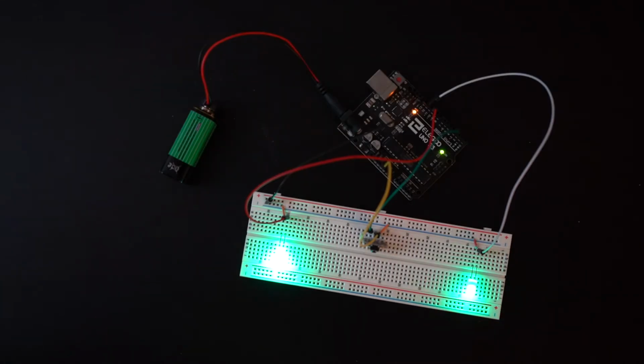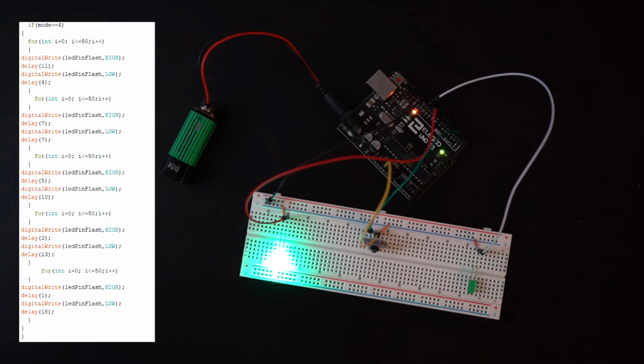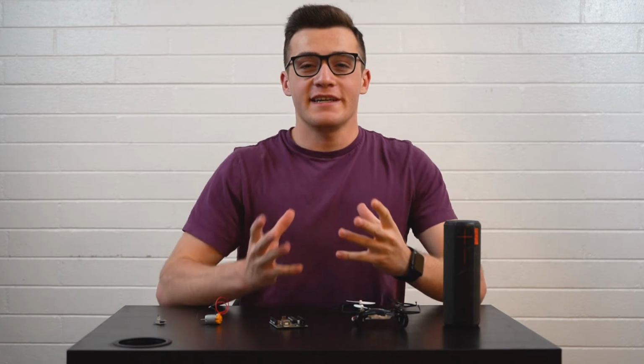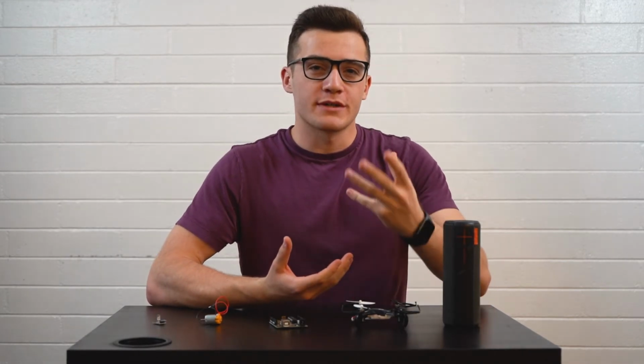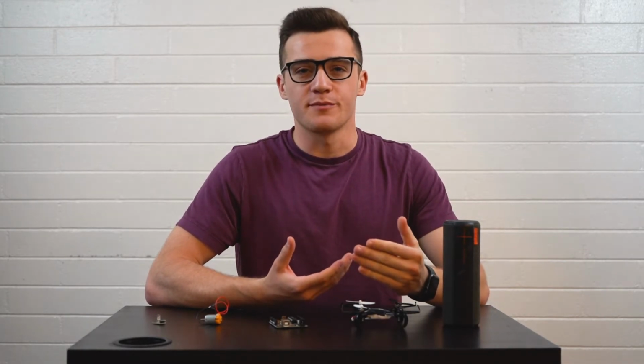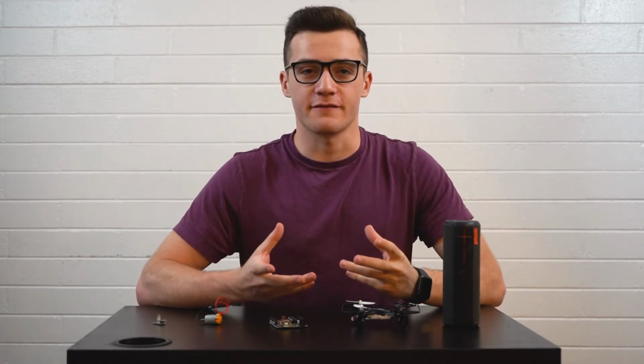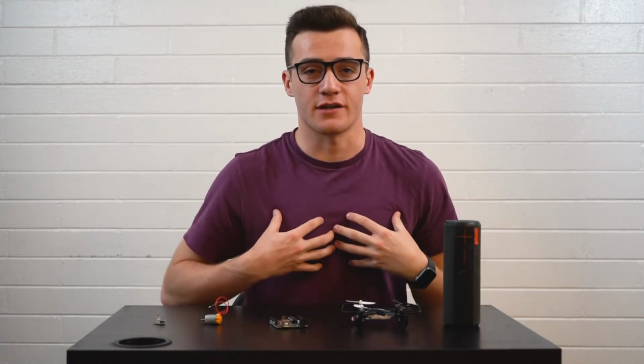And if you don't believe me, here's a code snippet showing that both of these lights are set to only high or low states. And again, the reason that the LED looks solid and not flashing is because we're flashing it fast enough such that the high frequency flashing is filtered out through the low pass filter that our brain is. And this is what's so crazy about PWM. We were given something that is digital and could only be on or off, and just by changing the width of those pulses, we were able to make it, for all intents and purposes, analog for us.